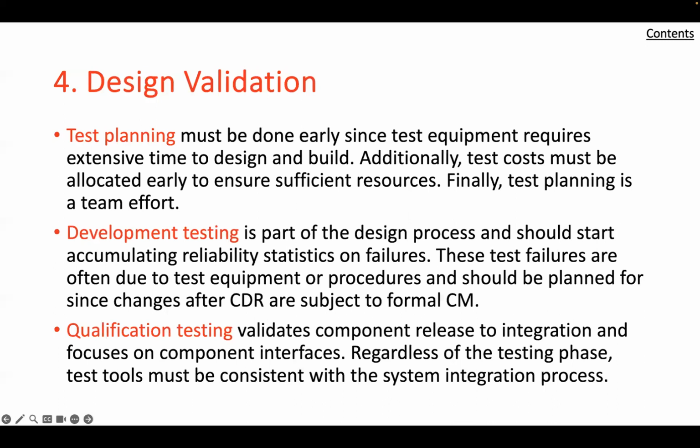We also have to be considering reliability and maintainability data. While during development, components may not be built from the identical parts used in the production article, it is good practice to begin collecting reliability statistics as early as possible by recording all failures during the operation and test and identifying their source.